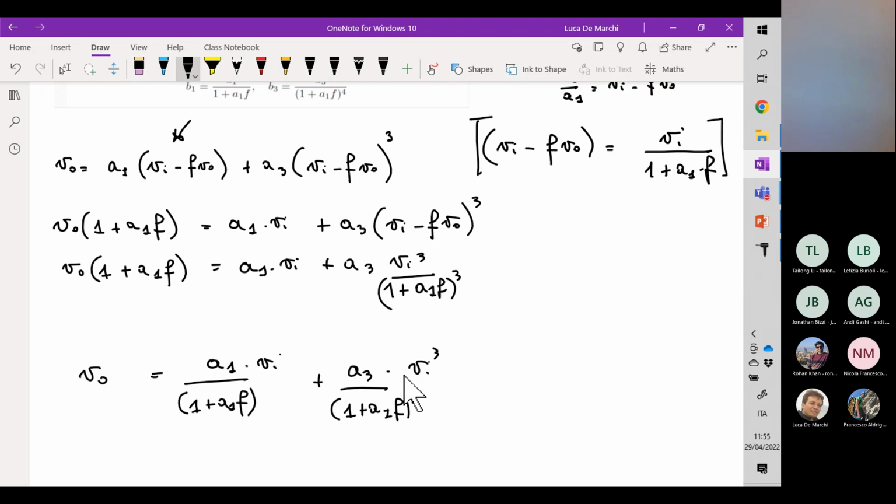Okay, so the idea is that the higher the input impedance, the better, because in this case we have a voltage divider effect which is negligible, if Z sub I is very large. Because the VI is Z sub I over Z sub I plus RS, the parasitic impedance associated to the source. We want this quantity to be as close to the unity as possible.